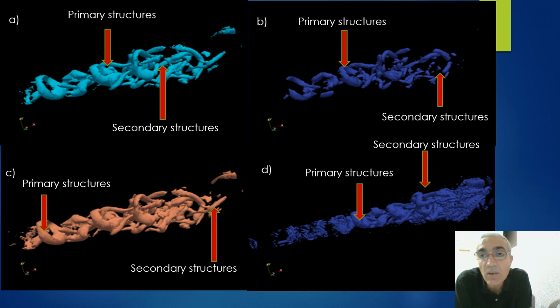Figure 4 is a graphical representation of the vortex structure detected by the different criteria: delta, lambda 2, Q, and omega. It can be seen that all criteria correctly detected the vortex structure, also the center of the structure. The four methods have a great similarity in the identification of the global vortex structure, but there are still differences in the local area. It can be noted that the longitudinal vortex connected the outside of the upstream ring with the inside of the downstream ring, which has the effect of accelerating the vortex winding.